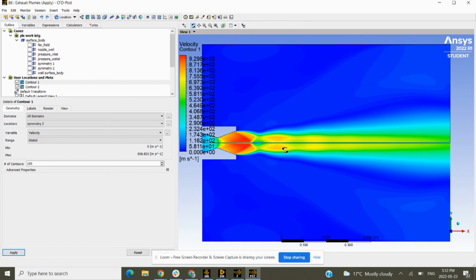And another thing is that looking at the flow, the Mach numbers do fall off at the end, meaning that it isn't the strongest flow. You usually want a stable pattern with the Mach numbers. So it's probably because the exhaust plumes aren't fast enough. So to boost this, I would probably compress the throat a little bit more just to get to the speed of sound. These two are just some inefficiencies with this rocket engine, and it shows you the potential that CFD has in analyzing these aspects to make sure that your rocket engine is as efficient as possible.